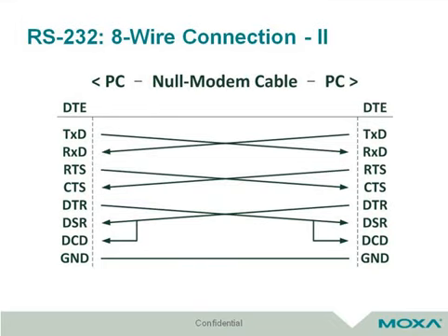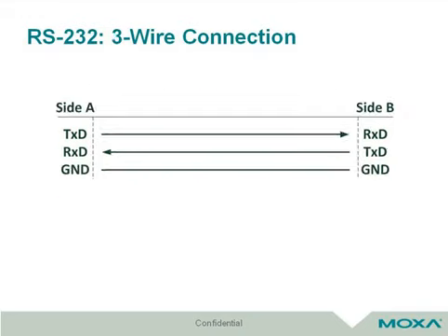This is a more modern way to use serial communication. Since two sides are DTE, we need to cross-connect the pins. As you can see, the DSR pin is shorted with DCD. This is to ensure all types of software can work, such as serial console port on rack server. This is a simple way to use RS-232. It uses only transmit, receive, and ground pins.